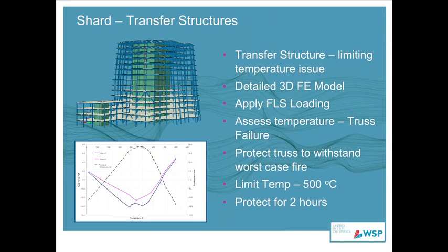So let's go on to transfer structures. In terms of designing the transfer structure, what we're really trying to do is calculate the limiting temperature at which these structures will fail. Transfer structures which include inclined members can be particularly susceptible to local heating.